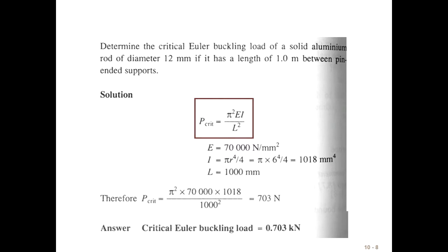Now, usually I always put everything into millimeters and newtons. Like civil engineers might work more towards using meters and kilonewtons because we're working with much larger forces. I think, you know, the aerospace people and the mechanical, you're going to be dealing with smaller forces. So it's highly likely that you'll be putting everything into millimeters and newtons.